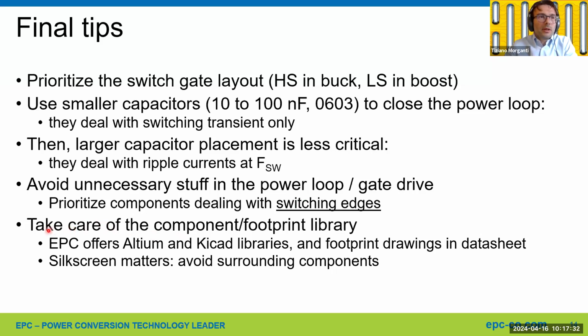And also, you need to make sure that the components in the footprint library are correct for your application. At EPC, we offer Altium and KiCad libraries, and we also have a footprint drawing in the datasheet. And also, to not be overlooked, silkscreen matters.